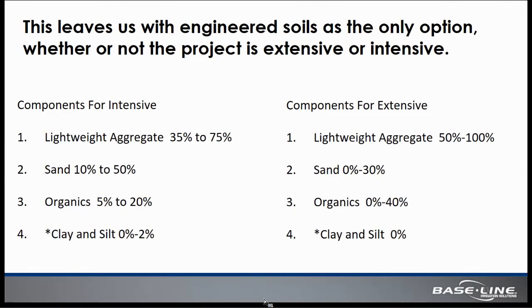So depending on whether the project is extensive or intensive, the blend of these different medias may alter or change and will be variable. So for an intensive application, you're going to have a lightweight aggregate that's going to be in a little bit smaller proportion to other sand or organics that may be present in that soil profile.